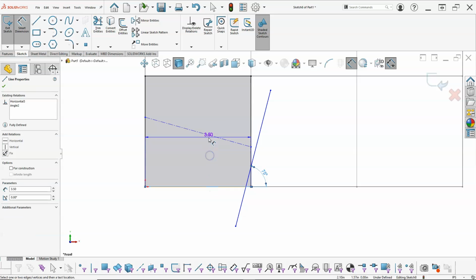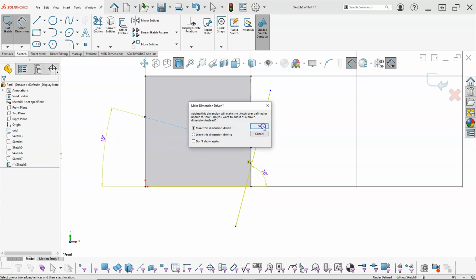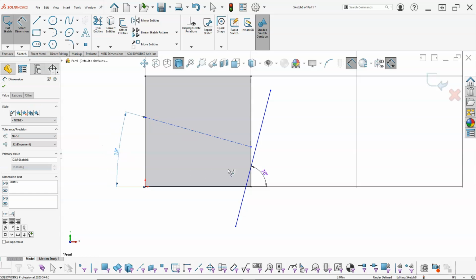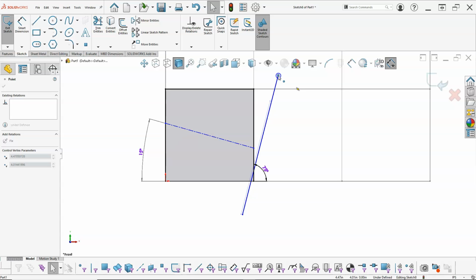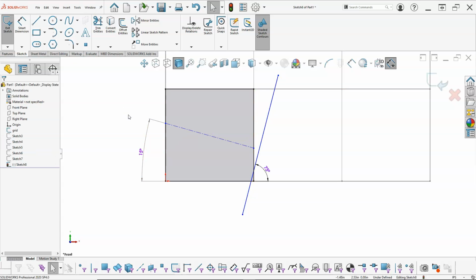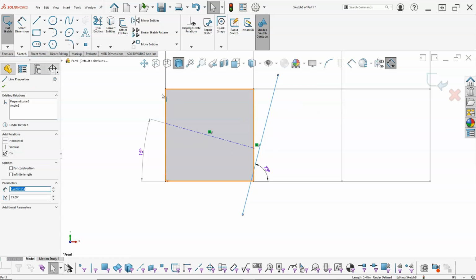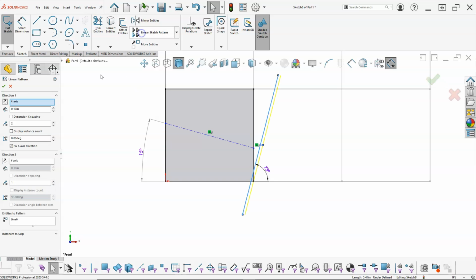And then if this was creating our geometry, then we have the 15 degrees along the linear. And there wouldn't be too much of an issue just keeping it along the x-axis. These lines would have to get that much longer. All right, so maybe we'll try that since I've been doing the angles to get it started. All right, let's do the linear sketch pattern. What it's not going to do is the 0.5 along the x-axis is going to have that little sine or cosine error that will be corrected when I apply the finished dimension.